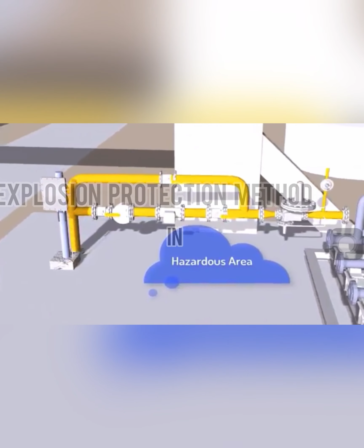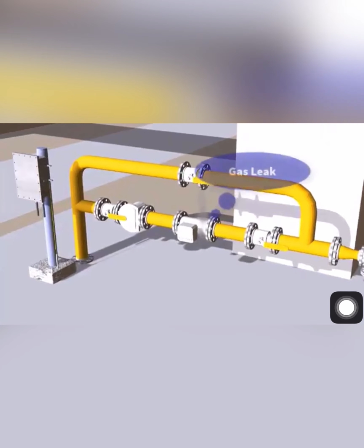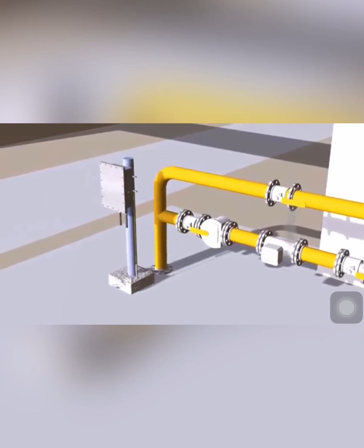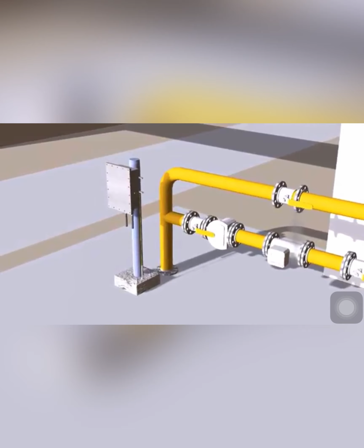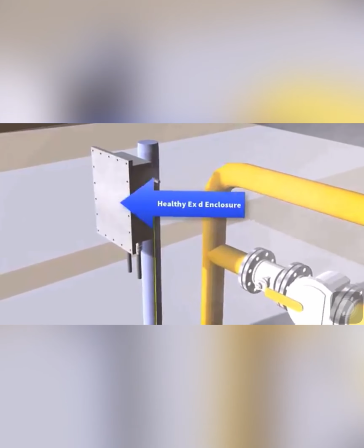There are three classes of explosion protection method. First one is primary explosion protection. Primary explosion protection aims at substituting something else for the flammable substances or the atmospheric oxygen, or reducing their quantities to the point where there is no danger of an explosive mixture forming.